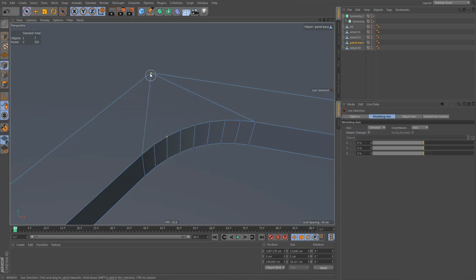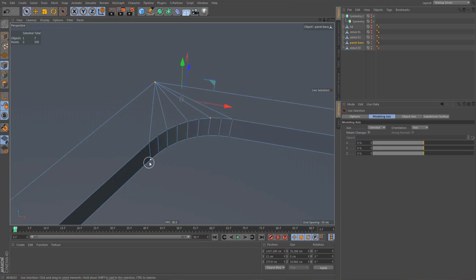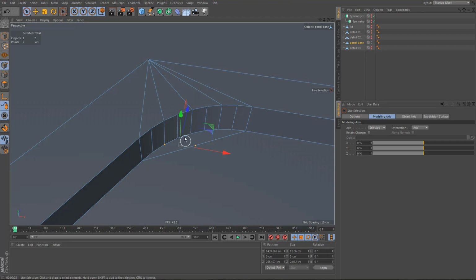And let's clean up the mesh by connecting these points. And over here, I'm going to connect these 2 points, then use connect points edges on this edge to create a point at the center. And again, I'll remove the n-gons here.